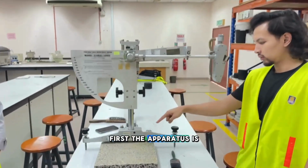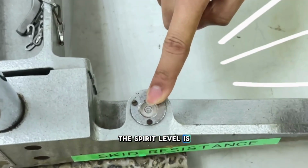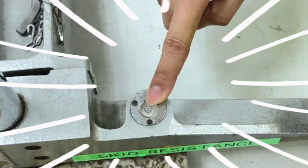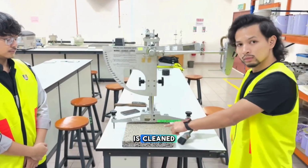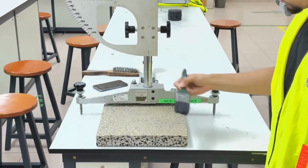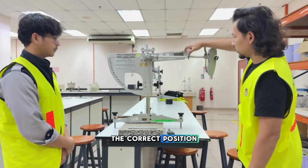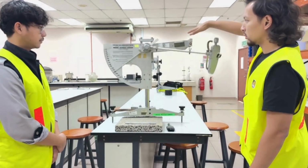First, the apparatus is stabilized by adjusting the leveling knob until the bubble in the spirit level is centered. Next, the test surface is cleaned using a brush to remove dust and loose particles. After that, ensure the pendulum arm is in the correct position and not positioned like this.